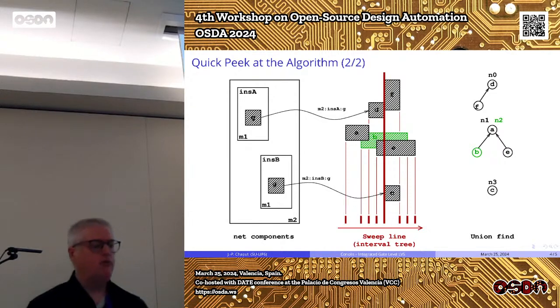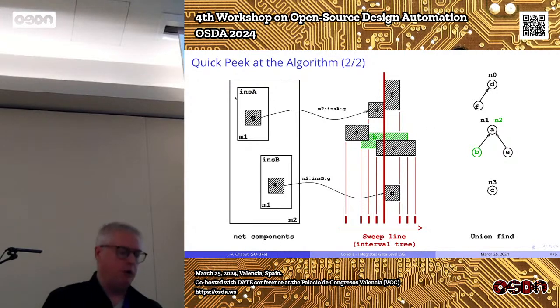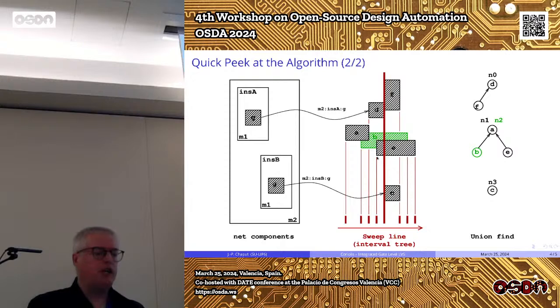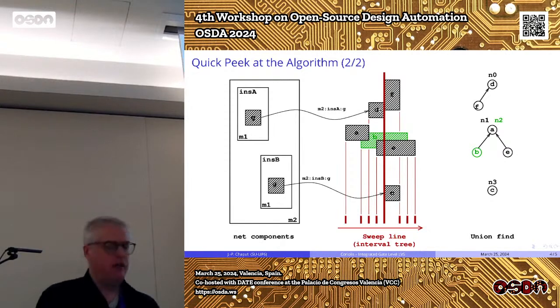So now, how is the transhierarchical flatten done? As I said, I do not fully flatten. On the left side of the screen, is the mouse working? Okay, very good. You have model 2 here and the instance B of the model, for example one piece of metal, in the virtually flattened layout. You have the first one here, and the second one here. We create, temporarily, in a transient way, a record of which rectangle each piece comes from. I don't know if it is clearly visible, but it's M2, instance A, and so on, while the second one is from the hierarchy, but they are also flat.